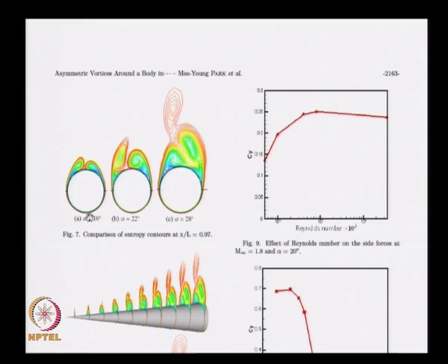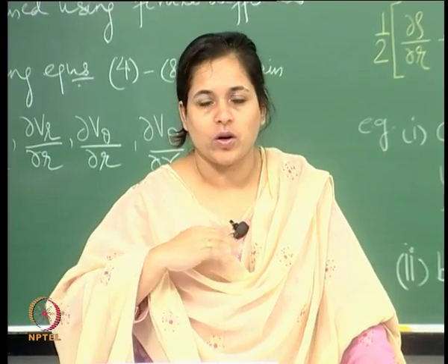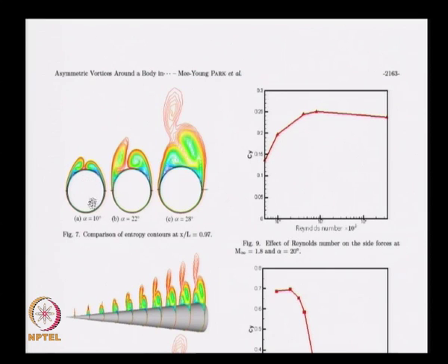What is more important, which we were discussing in the first couple of lectures when we started this, is how the vortex singularity moves away from the body as we increase the angle of attack beyond theta c. You can see that in play here. You have an angle of attack of 10 degrees. I have not read through this paper, so I do not know whether this is less than theta c, but you can think of this point still being attached to the body. Then you increase the angle of attack,